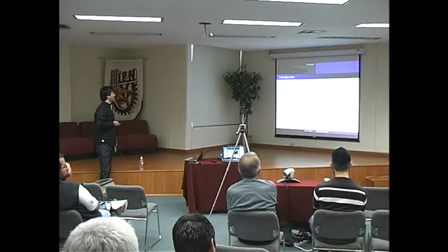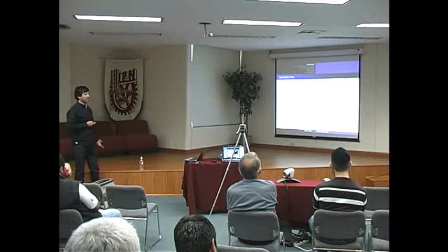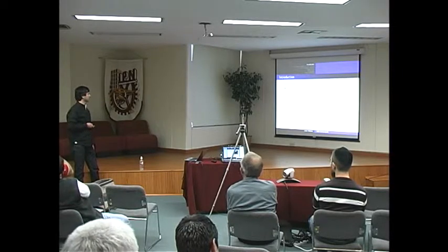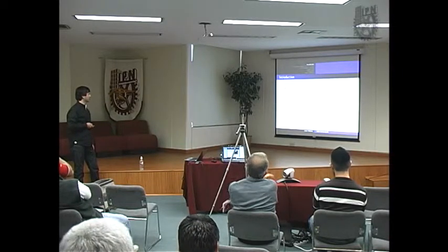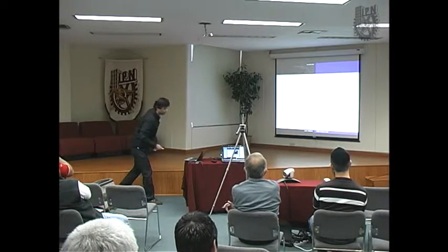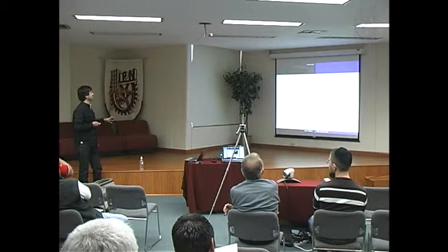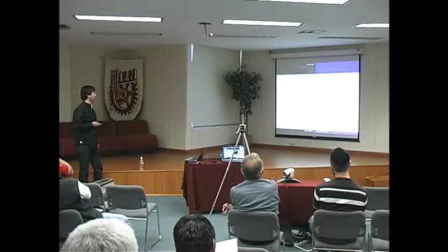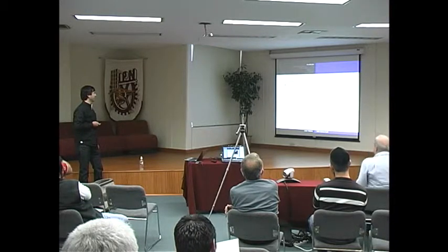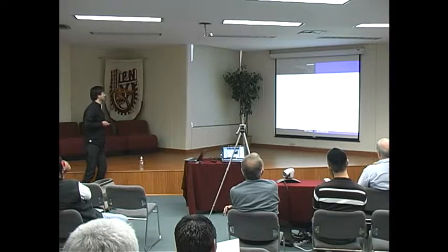They are concerned about nonlinear control schemes, but they are not worried about the problem of saturation of the duty cycle percentage. So when we realized this situation, we decided to look for schemes which consider the input constraint of the duty cycle percentage. We only found three papers on this subject.